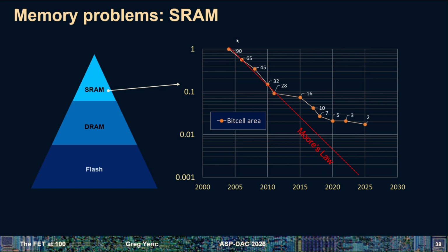Back in the olden days, when I did this stuff, the gate length was actually pretty much the process node, and we've still shrunk the cells, even though we haven't been shrinking the gate length as much. But these are the node numbers, not reflective of the physical dimensions per se, but reflective of the next node got smaller than the last one.